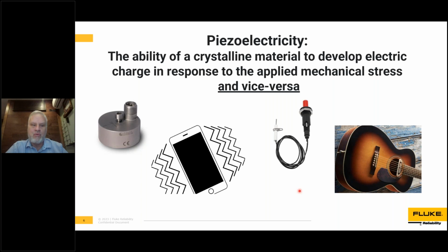Piezoelectric devices are used for accelerometers, things that we use to measure, which would be on the left here, and also on the right here. Some of the guitar pickups use piezoelectric sensors to pick up those vibrations and transmit them into an amplifier. It can be used vice versa, such as the thing that vibrates your cell phone, which is a piezoelectric device, or your typical charcoal igniter. When you snap that switch and it gives you a little spark, you're striking a piezoelectric crystal that gives you that voltage. So obviously that effect that happens within a crystal is very useful to us in these devices.